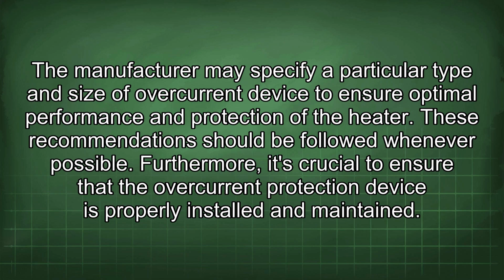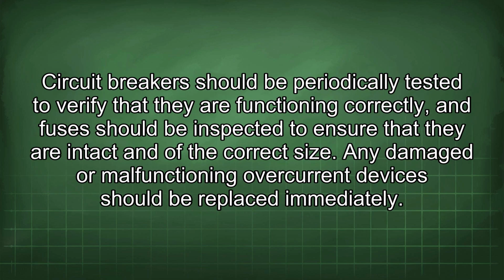Furthermore, it's crucial to ensure that the overcurrent protection device is properly installed and maintained. Circuit breakers should be periodically tested to verify that they are functioning correctly, and fuses should be inspected to ensure that they are intact and of the correct size. Any damaged or malfunctioning overcurrent devices should be replaced immediately.